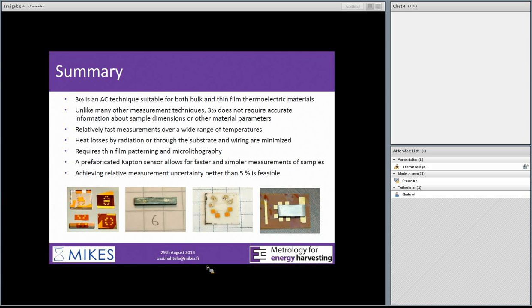You said that you use this differential method to obtain the 3 omega component with the lock-in amplifier. Wouldn't it be better to have some mixing techniques or PLL to produce a real 3 omega reference signal for the lock-in amplifier? Might be a good idea. We have been using this technique only now and not really considered other methods, but in future it might be a good idea to try different kinds of methods to detect this third harmonic component. Yes. Thank you.